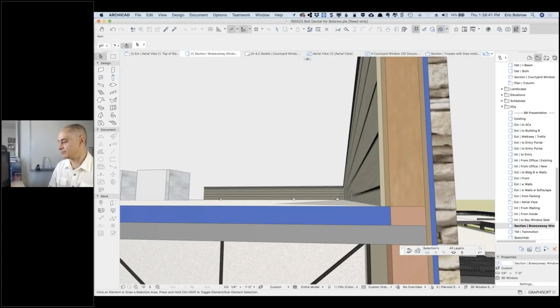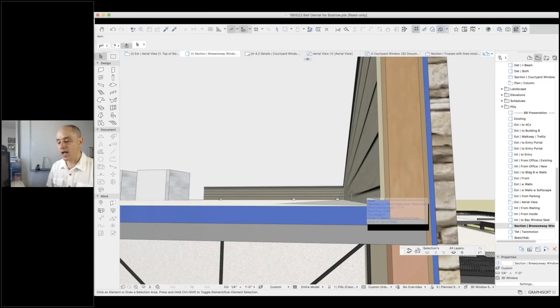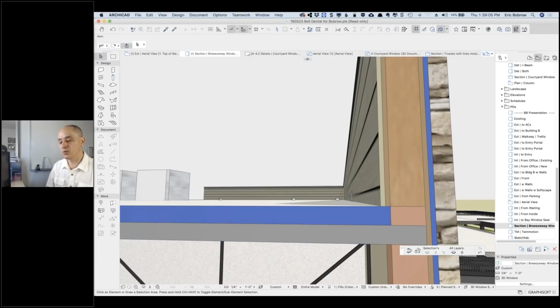As regards the priorities of the building materials, do you ever duplicate and create some that change the priorities for the same materials? Yes, occasionally, but essentially you want to do that only when there are no other solutions. For example, if we made this steel deck higher and it caused a problem somewhere else, okay, then maybe we need to have a lower priority steel deck and a higher priority one. Occasionally you'll need that, but in general, most of the time, if you get them in the right order, they'll work because they fit in with construction practice. You know, what elements are stronger.